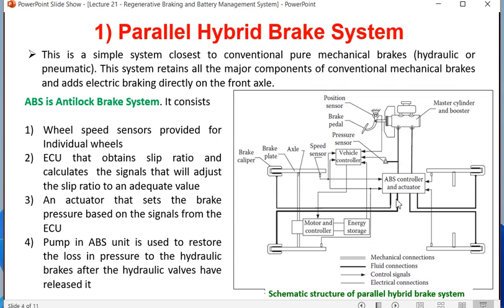There are a lot of other controls there. There is a pressure sensor. This pressure sensor ensures that inside this brake fluid line, a sufficient amount of pressure is maintained. Okay, and after that, through these fluid lines, the fluid goes to the caliper. Caliper is a kind of gripping mechanism which grips the disc which is connected to the tire. As soon as the liquid goes inside the caliper, the caliper holds the disc. So if more brake force is required, there is actually mechanical braking.